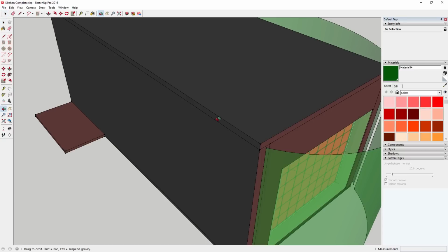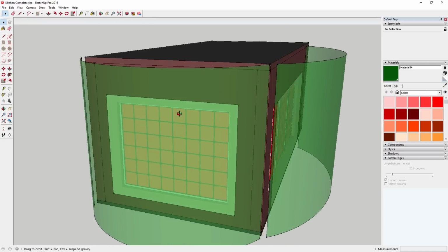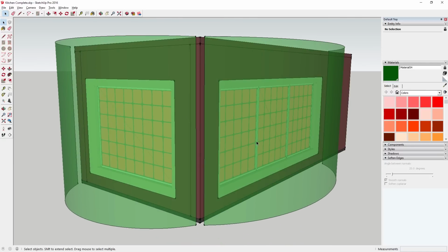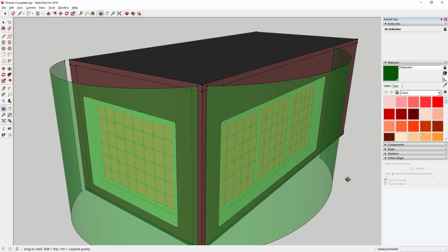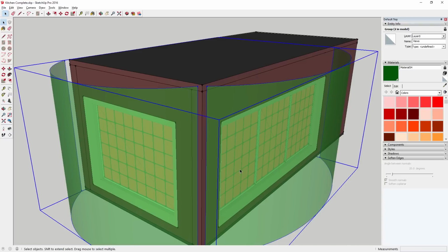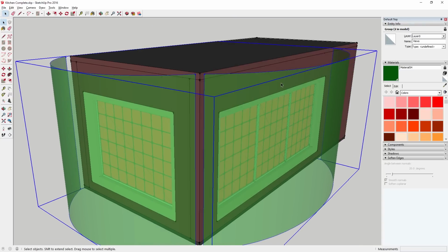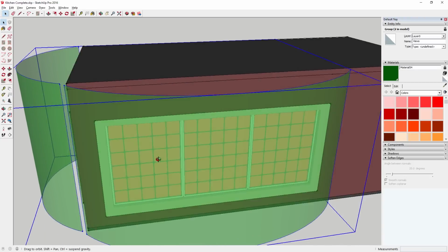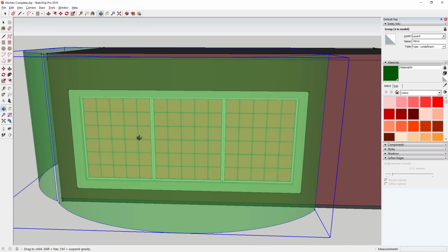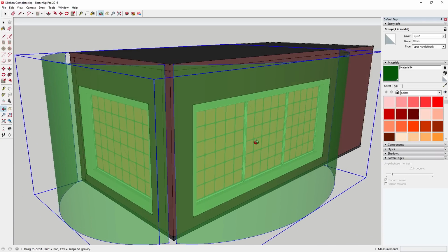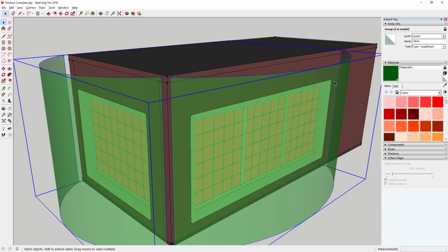First is on the outside. Let's say I don't have the perfect HDRI to give me the lighting or the view I want out of my window. So what I can do here, and it's these green circular planes that are outside the windows, I plan for that, and I can actually throw an image on these. I don't know if it's a hack or what, but I picked it up a long time ago looking at some other interior renderers. But that allows us to place any image we want outside the window.